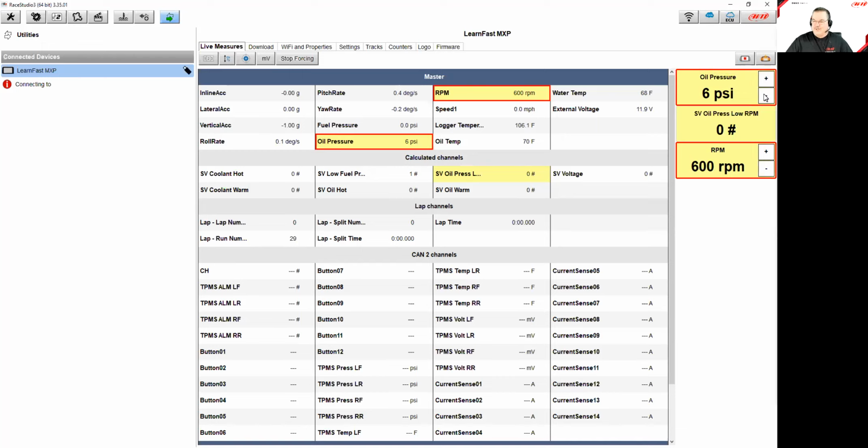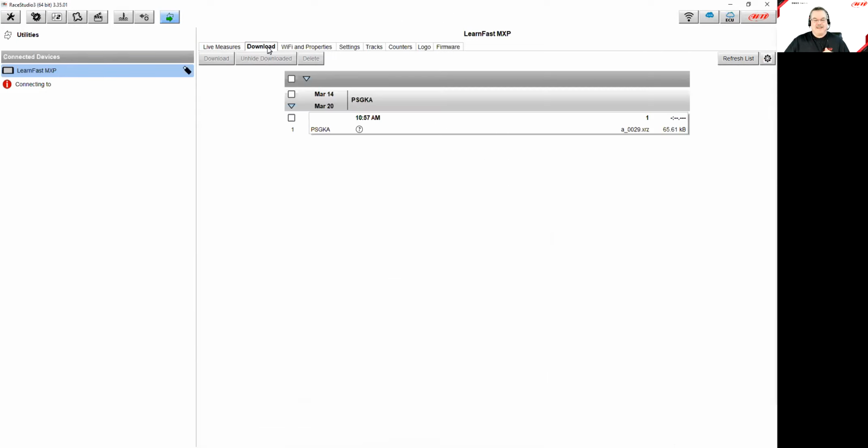And if I were to come down here and do things to make this go away, and then start it up and make it come again, we're going to see that status variable is 0 to a 1 inside the data that is logged. Okay. And then I'm going to stop that data logging, and boom, it's done. So now we could go right over to the download page, and there's that test I just did, and we could download that and check it.